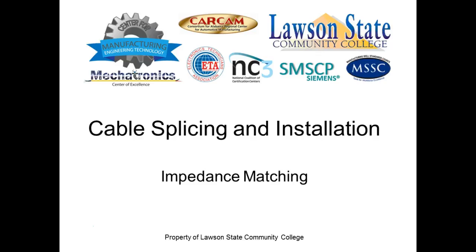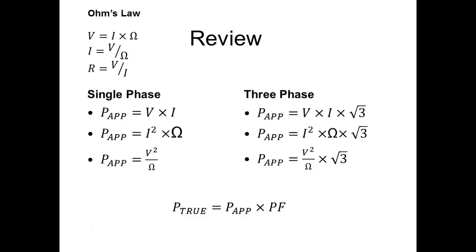So our voltage is our force, right? We use it as the force, and then the electron or the current flow is what we use as the speed. And then we have several other formulas that are derivatives from that because of Ohm's law. So Ohm says that V is equal to I times ohms. So if V is equal to I times ohms, then what we can do is we can come down here and substitute I times ohms, right? You understand that? And that would give us I squared R.